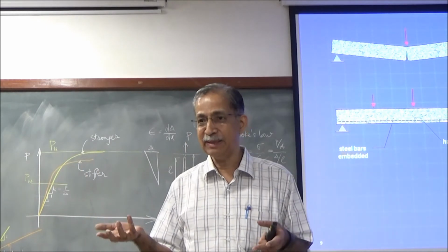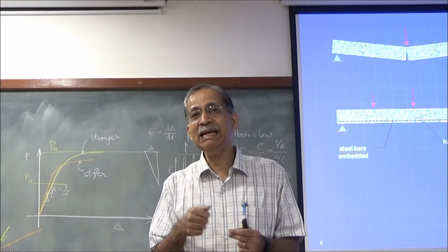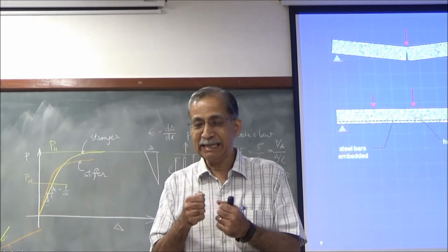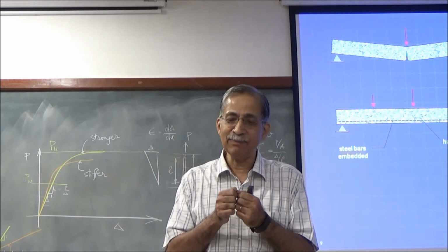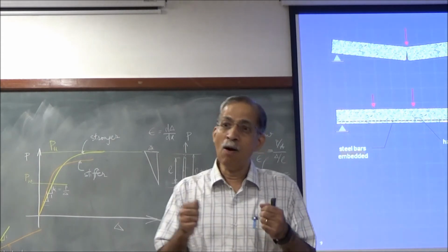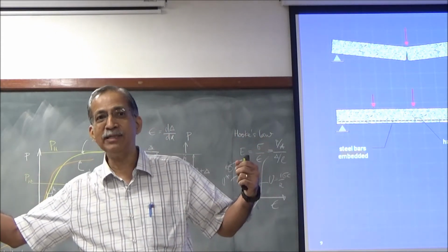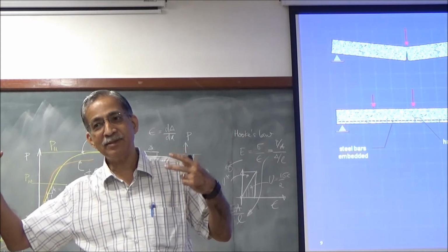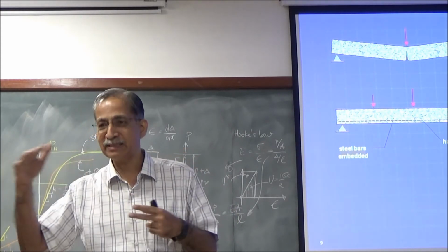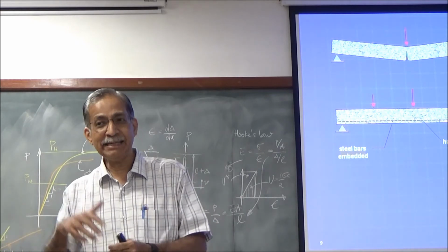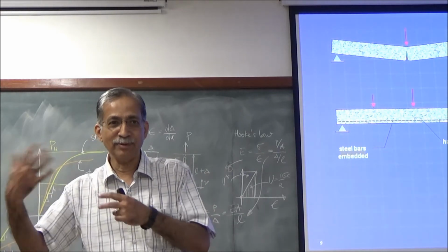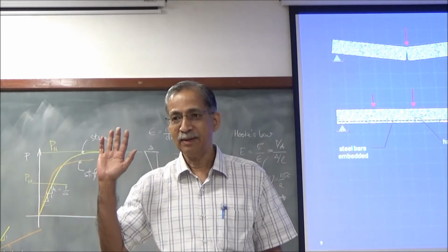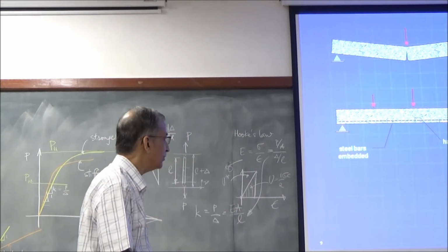Damping will release some energy. But more important, yielding of steel. So steel is yielding, and steel has this fantastic ductility property where it can go on yielding for a long time without letting go of its strength. That's called plastic behavior. And heat is generated in that. So, that's how the energy is dissipated. It's absolutely necessary. So, ductility is the way.